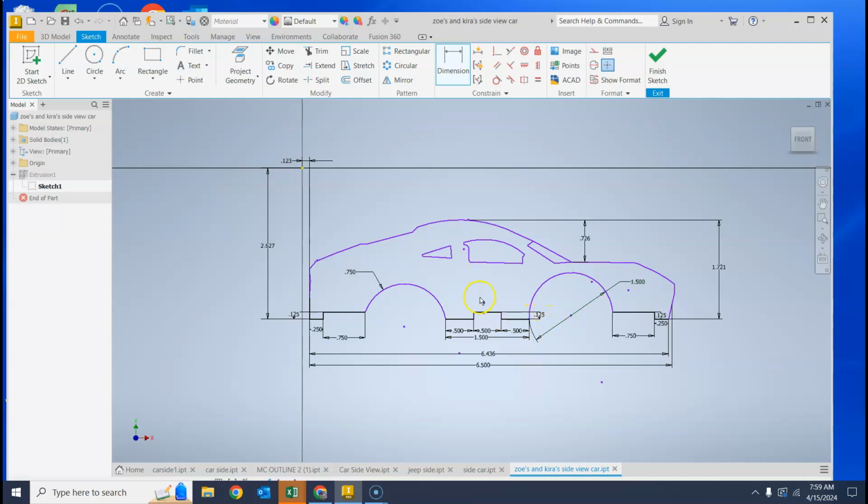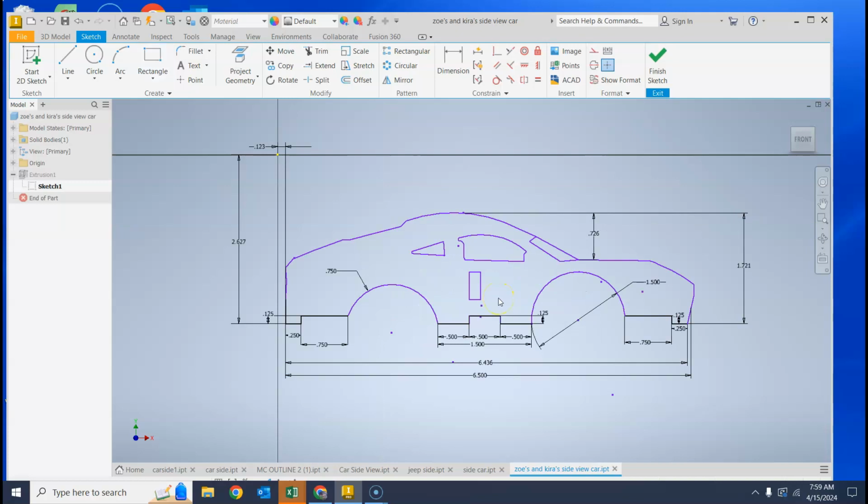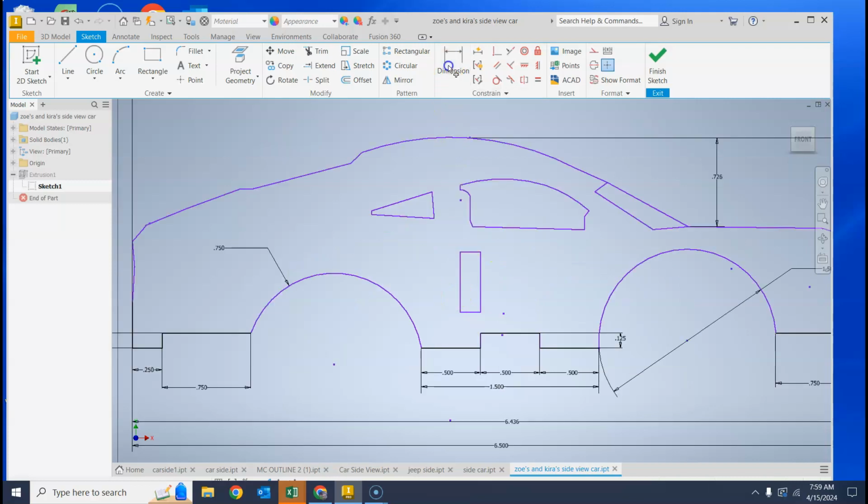Now, if you're going for level 3, you should also have a rectangular piece, somewhere in here that's bracing your design. I don't know where, be careful, it could go anywhere. So after I draw that, I need to have a specific size, and some people are putting on their paper and pencil sketches a dimension, let's say 0.135 by 0.5, something like that. But then they think they're done, but just because you dimension that rectangle does not mean it has a location, right? It can still move. So I still need to reference it to a black line to have a specific location, or line it up with another corner that's black.